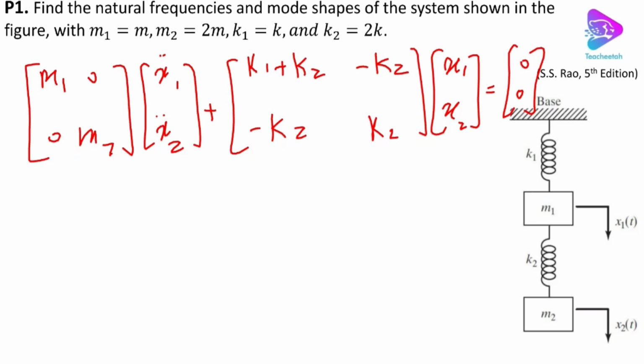I'm sure you can find this matrix based on the equation of motion that we had before. It's pretty simple. You remember we explained that we can take x1 as X1 cos(omega t plus phi), and that's why we expect that our system behaves harmonically, right?